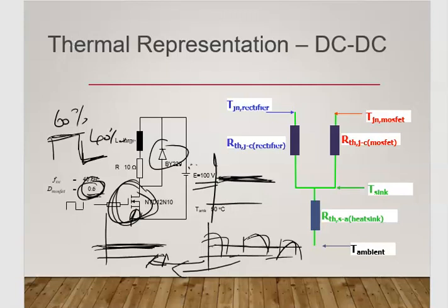During the on cycle, the current flows through your MOSFET and returns to your source, so 60%. During the off cycle, the remaining current that we pumped into our inductor needs some path to deplete. If not, you cannot switch on your MOSFET because current still remains in your circuit, and it will create spark and backfire.